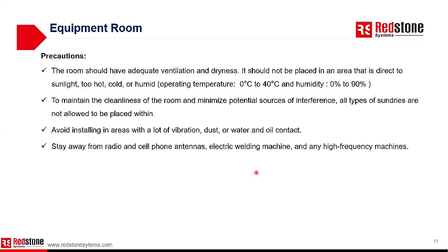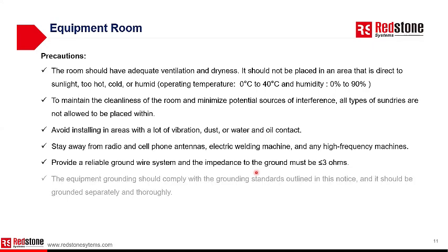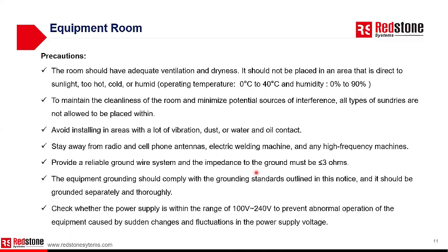You need to provide a reliable ground wire system, and the impedance to the ground must be less than or equal to 3 ohms. The equipment grounding should comply with the grounding standards outlined in this notice and should be grounded separately and thoroughly.